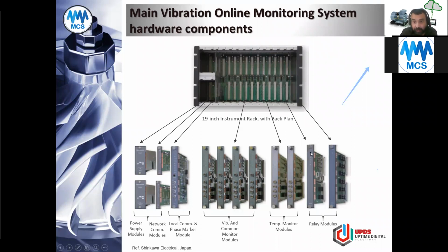Some condition monitoring systems are equipped with vibration; you will find storage, communication, and relay all in the same card. They still fully comply with API 670, but they are a bit deviating, let's say a deviation in superior.